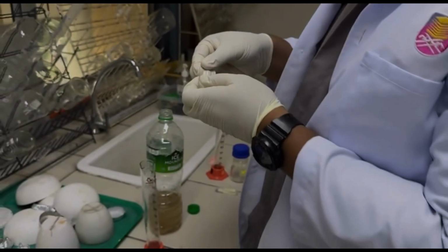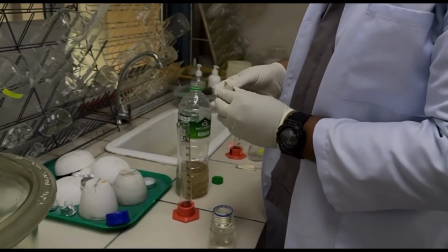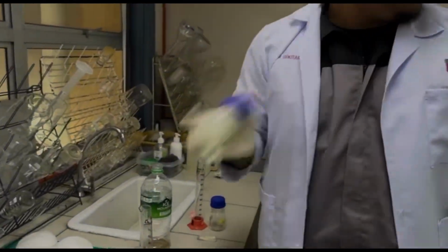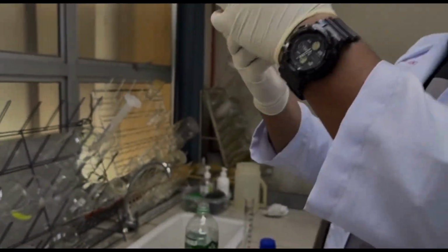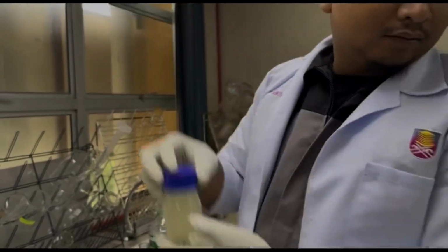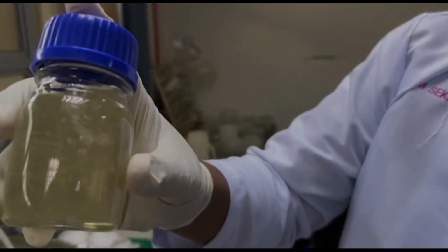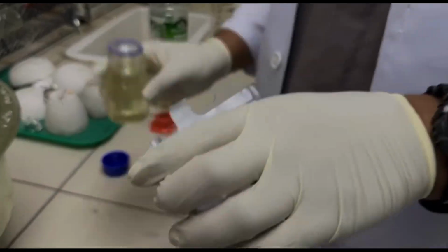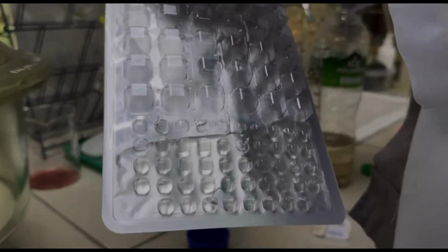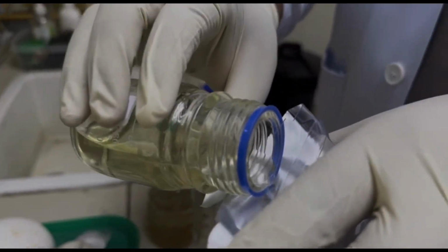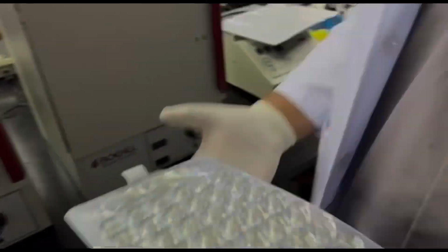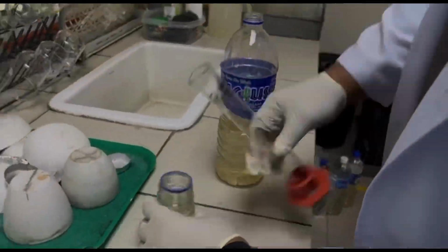Insert one portion of Colilert into the glass jar. Put on the cap and shake the glass jar until the Colilert is fully dissolved. Pour the sample solution into an E. coli sample tray. Keep the pouring angle at about 45 degrees to minimize air bubbles. Place the E. coli sample tray into the sealer mold and seal the sample tray with the sealer machine.